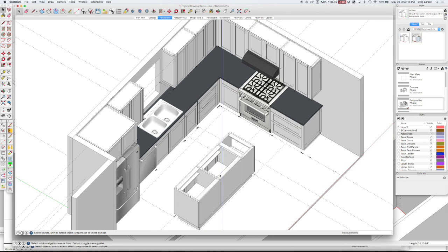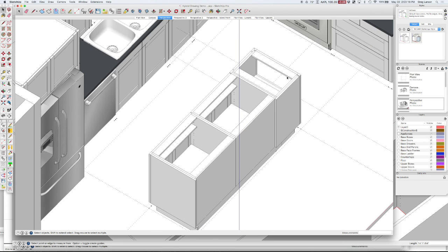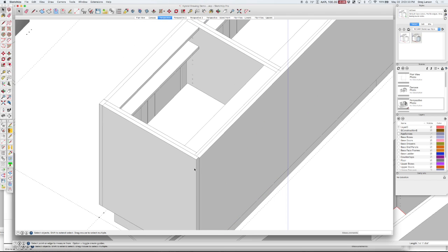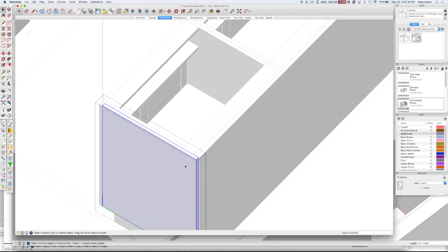And I've got a partial sheet going down this side, but it's a simple matter, since it's just a SketchUp component, to unlock it and pull it down to meet this guy. You'll also notice that I need to pull this one just a little bit, so I triple click on it because it's just a SketchUp component. Choose the push-pull tool up here, which is the P key, or this tool, and I'm just going to pull this out to meet it.